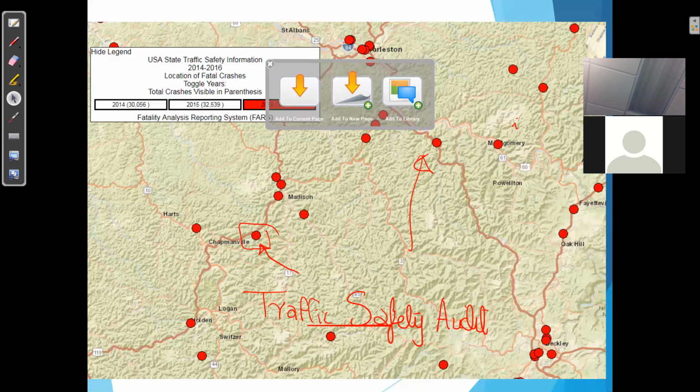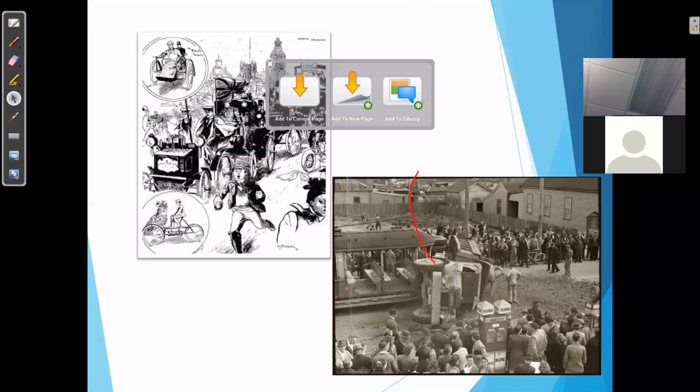These hotspots come from older data. We have repetitive crashes on these red hotspots. How can we improve that, and how can we reduce the number of crashes there? Figure out what went wrong in the design. Do we need more lighting? Do we need to reduce the speed? What's wrong there? This is what we call hotspots. And it's really interesting and easy for us to do with the use of the computer and GIS. People who have GIS use mapping and data, and they create these hotspot maps.